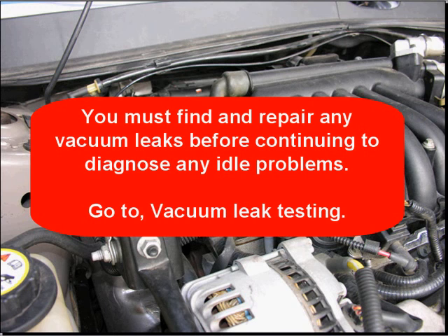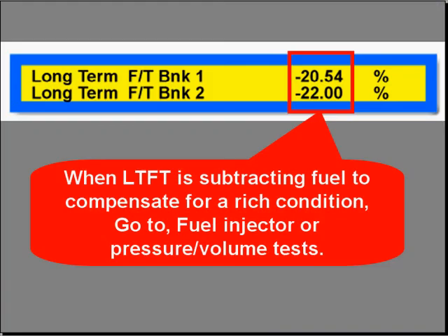We have worked on many vehicles referred to us where the technician swore there were no vacuum leaks, and after we tested it, we found vacuum leaks. So check and double check. When long-term fuel trim is subtracting fuel with the minus sign, it's trying to compensate for a rich condition. Go to fuel injector or fuel pressure volume test.